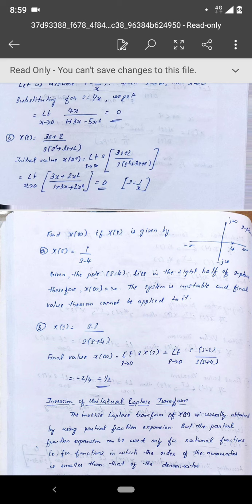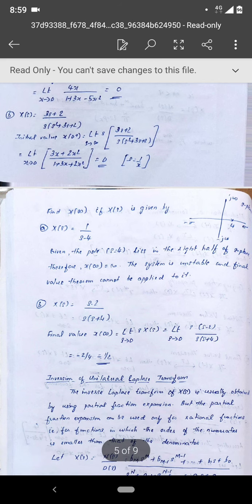Okay, so I hope you have learned in control systems what the significance of a pole is. What is a pole? If you equate the denominator to 0, you will get the poles. If you solve the denominator polynomial, then the roots of that denominator polynomial will be the poles. So the position of poles is very important. That is, you have the s plane. What is the s plane?